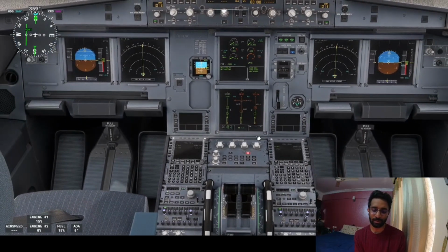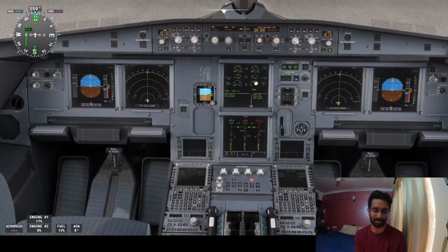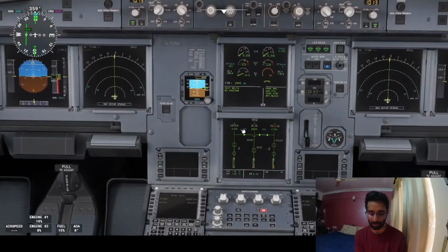Now next, what will we do? We'll start engine number 2. Like I said, it's a two-engine startup that I'm showing initially. When I start engine number 2, even though the brakes were set, ideally the PTU is inhibited, right? But the PTU runs now because this is the only chance for the PTU to do a self-test. Because the moment the second engine starts, it gets pressurized, right?